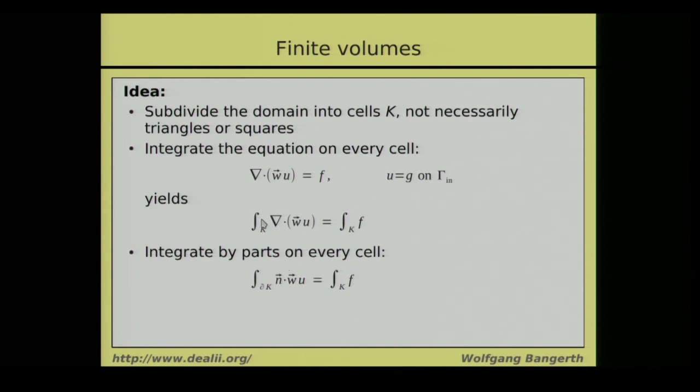That's essentially just integration by parts. You can think of this as, well, I have a 1 here, and I want to bring this divergence over. The gradient of 1 is 0, so the domain integral disappears, and all that remains is the boundary integral that comes out of the integration by parts. So this is the fundamental form that I have in finite volumes, and let me give you an interpretation. I'm integrating over the boundary of a cell. What do I integrate?